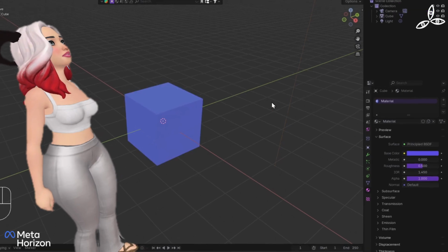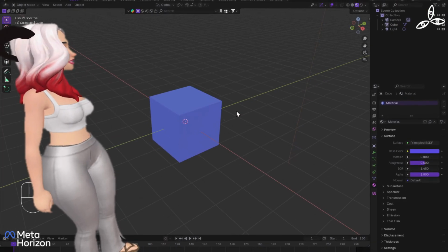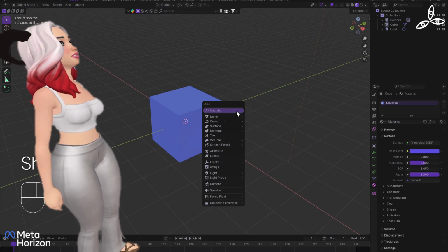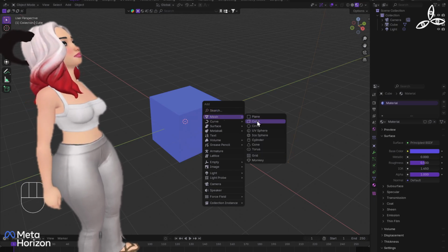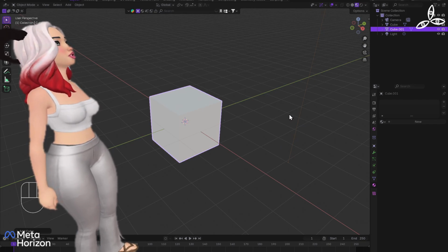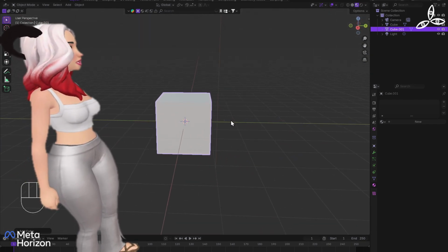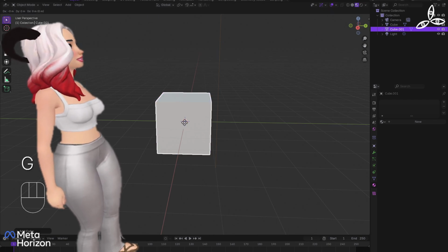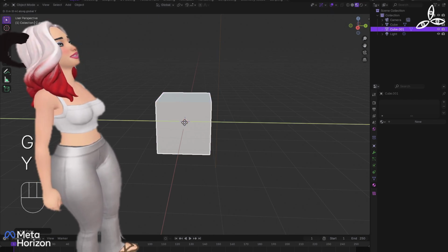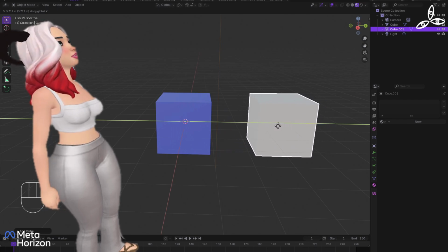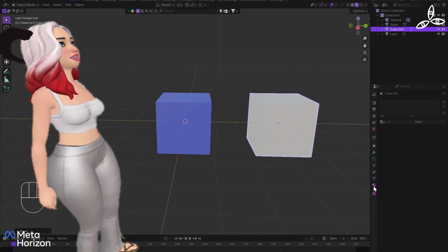And then if I add a new object, I'm going to press Shift and A to do that, and create a new mesh. It's going to be a cube. Now, similarly, you'll remember on course 1 last week, that spawns it right in the middle of the previous object, because that is where the 3D cursor is. So if I press G, and then Y to move it along the Y-axis, I'm now sliding across here.